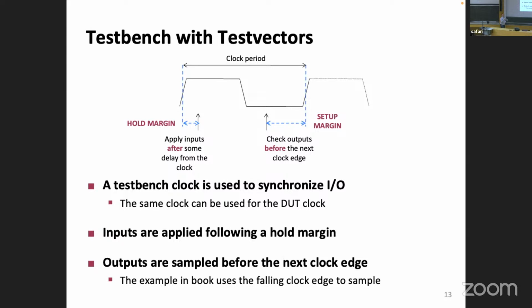I don't want to mix these two. I say this because the inputs that arrive at this time, if I'm a Moore machine, are for the next cycle. They won't become immediately visible. If it's a Mealy machine, this input will, in the same cycle, already change the output.